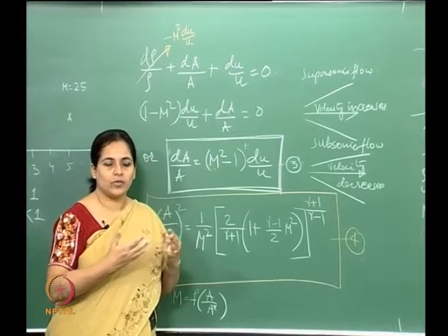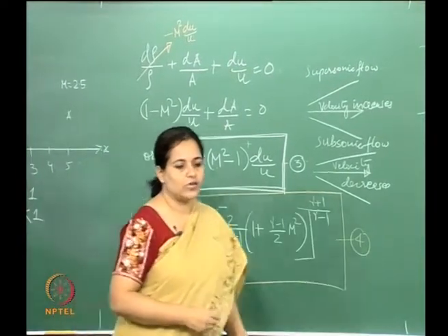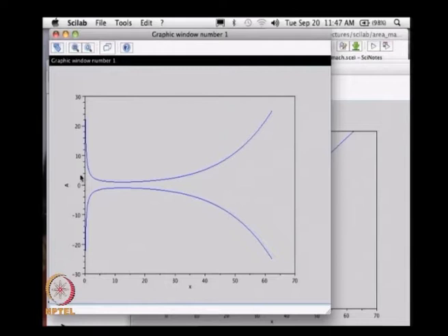And so, the flow, when it is going from converging to diverging, passes through this point, and what we get is a supersonic flow. So, what you have here is a subsonic flow that goes through this kind of area change and becomes supersonic. This is something that Laval had done a long time back. So, this is essentially your converging diverging nozzle.